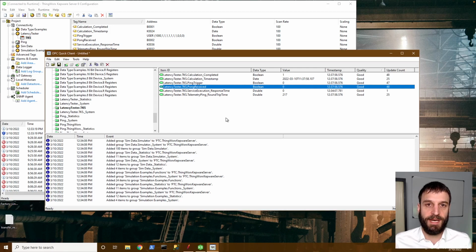So here we can see back on the Kepware side, I could pass these values back into a control system, whether it be a SCADA or a PLC or something, where the intention is, if I'm relying on such communications flow, that I'm going a little bit further than just doing a heartbeat up to ThingWorx. I'm actually bringing the communications back, and I'm saying that the calculations that I'm expecting to happen, like a scoring of a model or something, are actually happening on ThingWorx.